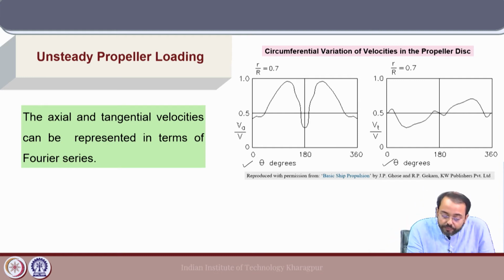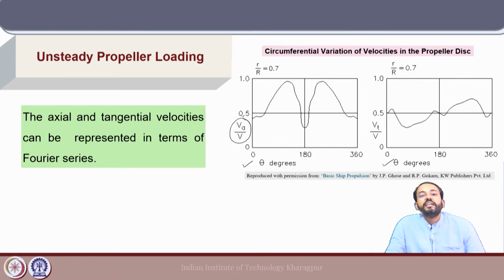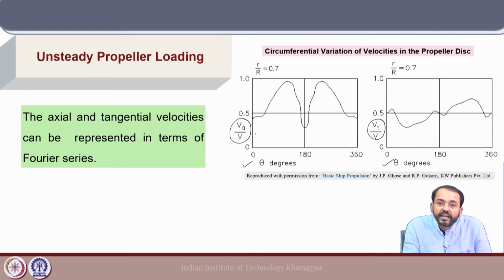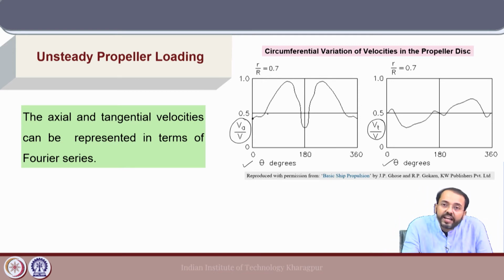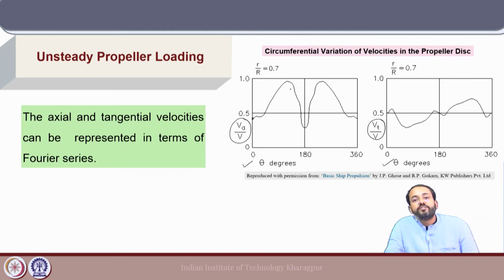For the axial component, it is non-dimensionalized by the inflow velocity V, and similarly the same is done for the tangential component. And we see here that the axial component has a very low value at theta equal to 0 due to the high value of wake fraction, and the value of Va by V changes drastically over different angular locations of the propeller blade.